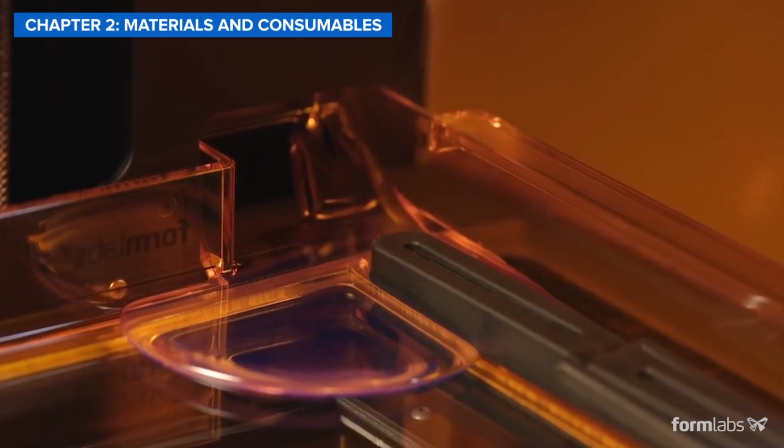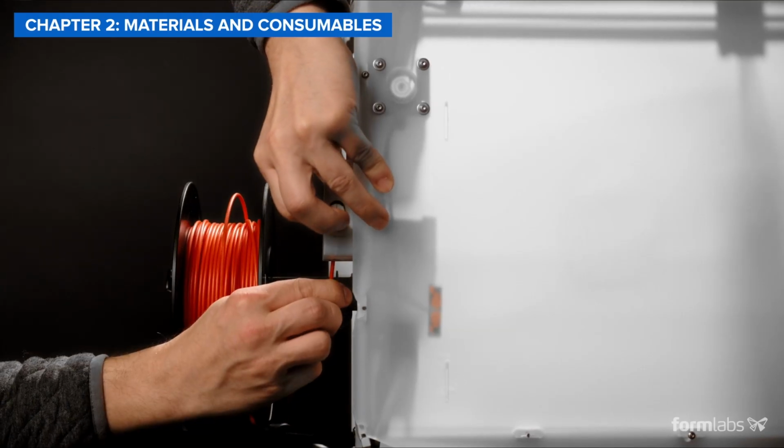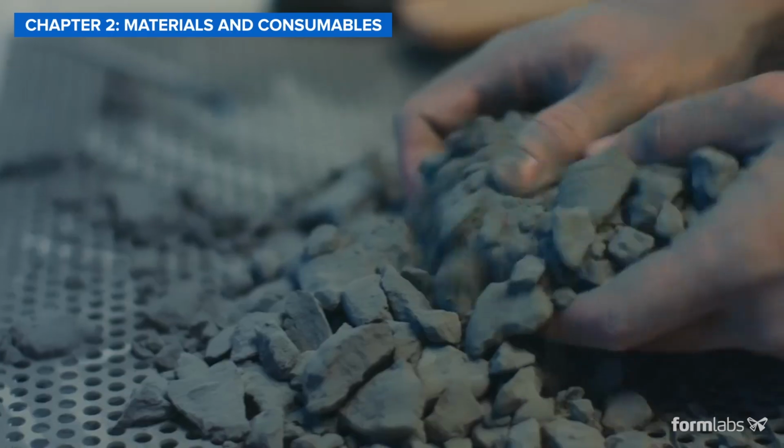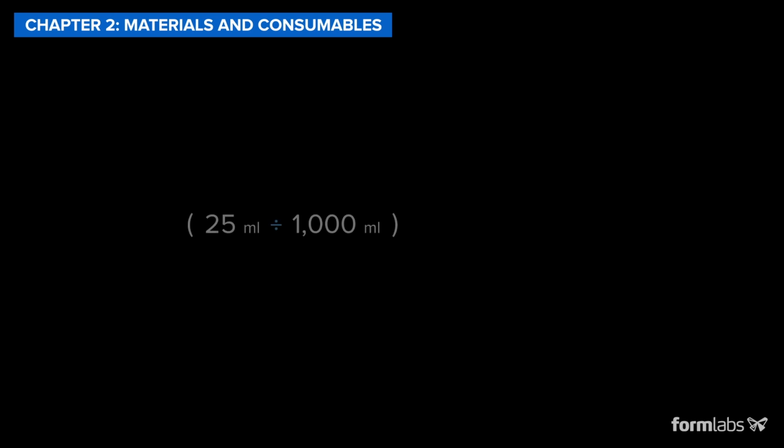Raw materials and other consumables required to create parts are variable costs that are highly dependent on the number of parts you're producing. When calculating material costs, measure the amount of material that's required to create a single part and multiply it by the cost of the material. Also, make sure to include support structures, waste, and any other consumables necessary to produce the parts.